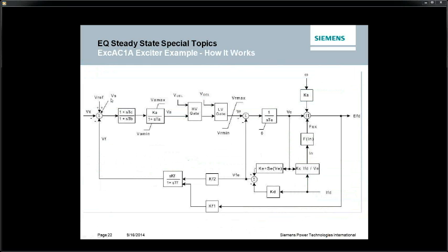So you can see you have your inputs and whatnot: your voltage, your compensated voltage, your system voltage, reference voltage, your high and low voltages if you have voltage limiters, and then the actual mathematics of this model, and how all those individual attributes that you define in the EXC AC1A class are applied in the equation and what decisions are actually made.